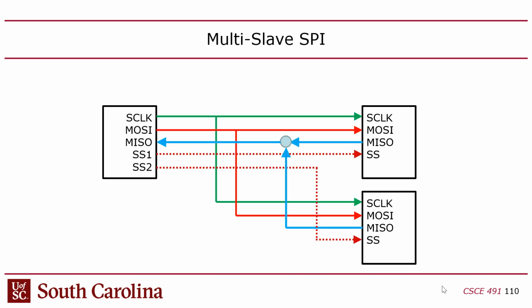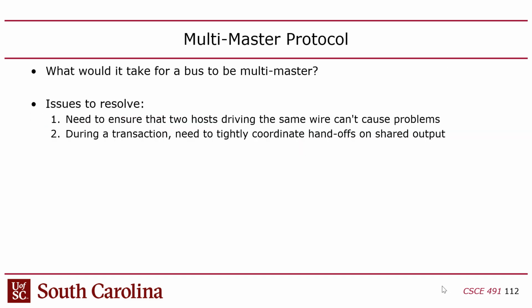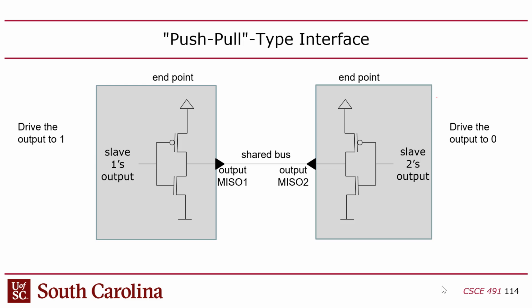And so the problem here is that most SPI uses what's called a push-pull interface or a driver interface. The way it works, if you have an output on a chip that's push-pull, that output is connected to an inverter inside the chip.